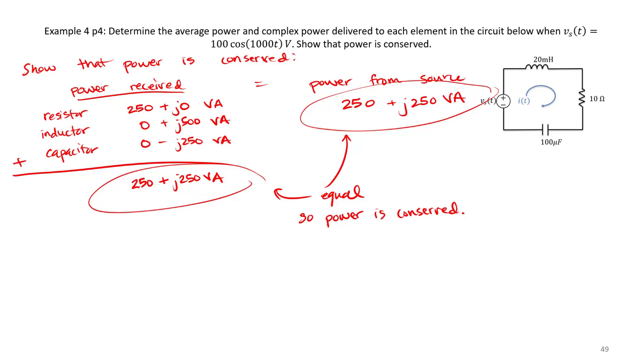So that's all there is to it. The key thing with complex power is to keep those toolbox equations handy, especially S equals V I star over 2. These are really important equations, and we'll see in the next video that by optimizing our complex power, we can design circuits that transfer power as efficiently as possible.